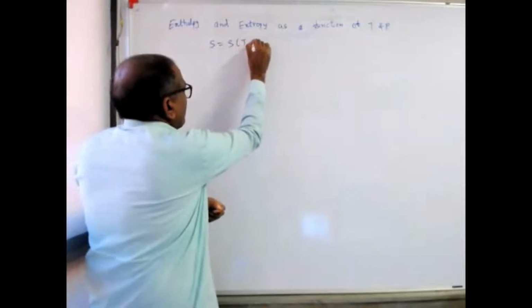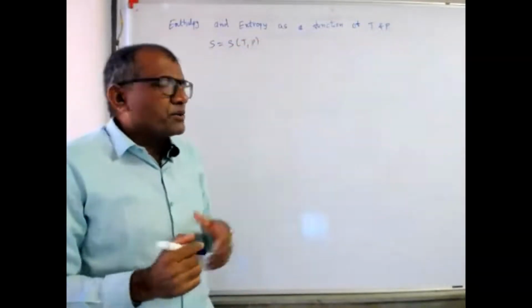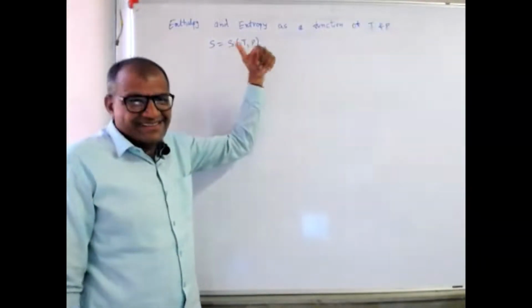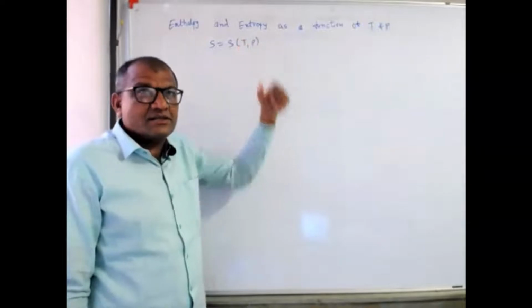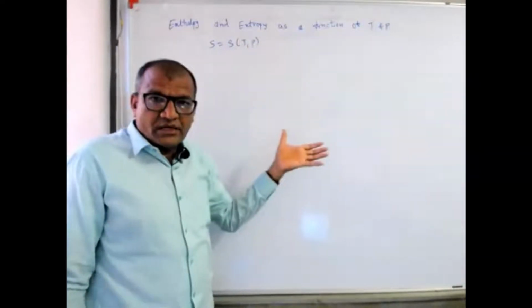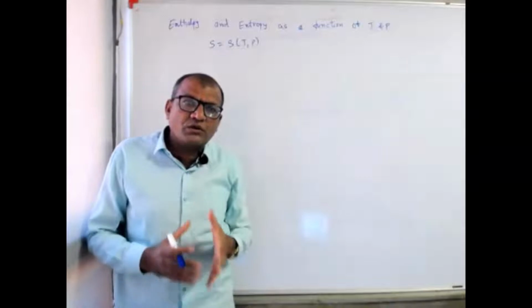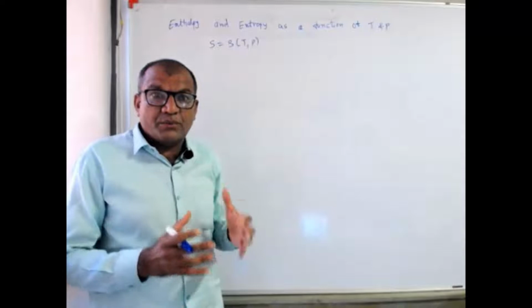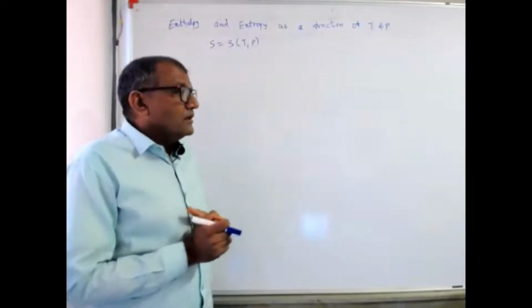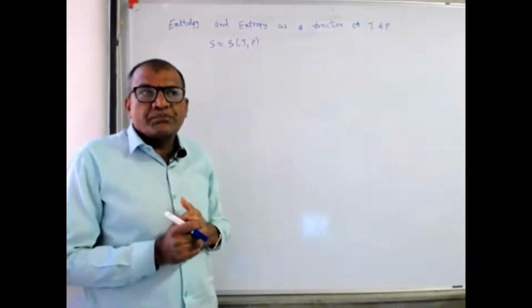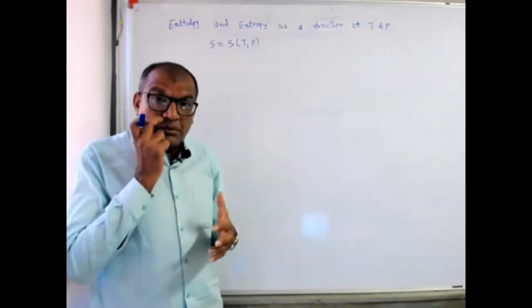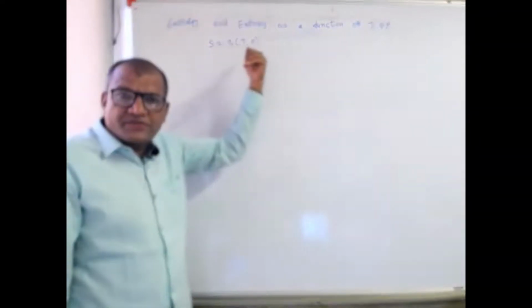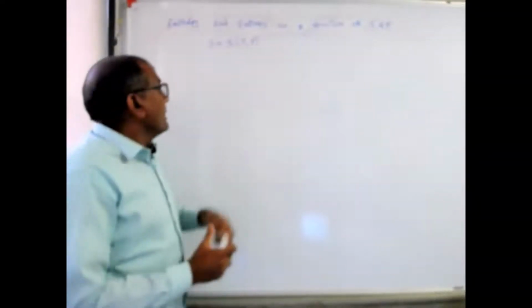In the first equation, I can write entropy as a function of temperature and pressure. Is it right? Yes, absolutely. The reasoning for whatever we are going to do is that this is for a pure, homogeneous fluid. For any pure system, any pure fluid, single component, the degrees of freedom is 2. So the minimum number of variables required is 2.